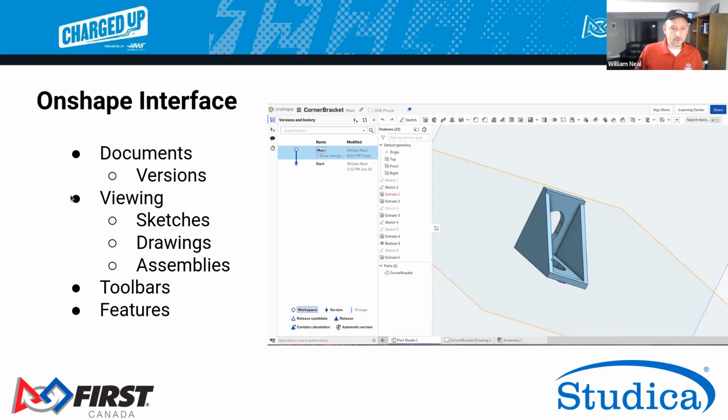Okay, so in the Onshape interface, here are 3 different views that we may use. This may not be all of them. The first is a sketch. This is a 2D drawing, and you can see on this little graphic here, there's a sketch button. If I want to make a sketch, I press this button. And first I have to select a plane on which to do the sketch. And you can see here in this drawing, this particular plane has been selected. There are 3 planes, the XY, the XZ, and the YZ plane to begin with.